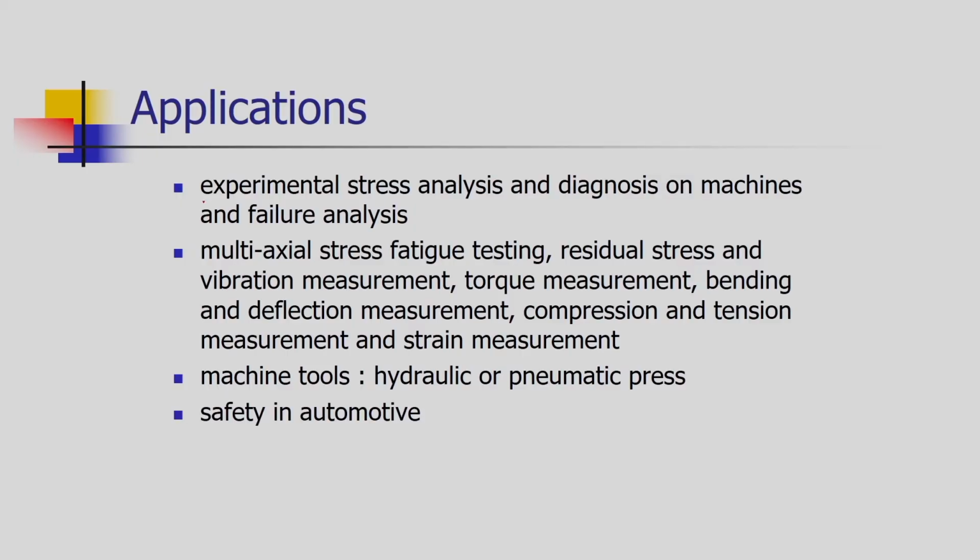Basically, strain gauges are widely used in experimental stress analysis. So, those who are carrying out MTech or PhD projects in mechanical manufacturing, basically in experimental mode. So, for stress analysis and for diagnosis of machine tools, strain gauges are widely used, particularly to measure the forces. Moreover, for fatigue analysis, fatigue testing, stress analysis, vibration measurement, as I mentioned just now, torque measurement, bending and deflection measurement, the strain gauges are used.